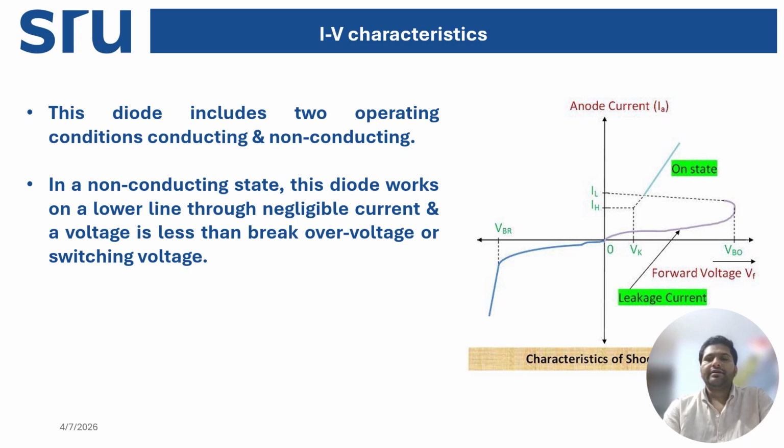It means that as the applied voltage increases up to the breakover voltage, the device starts conducting current. At the breakover voltage, the device suddenly switches on and the current increases rapidly. This transition is very sharp due to regenerative feedback.